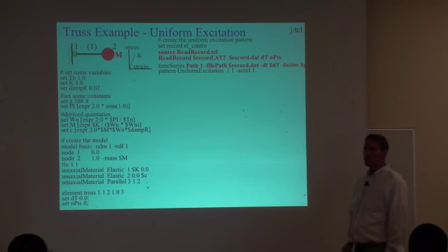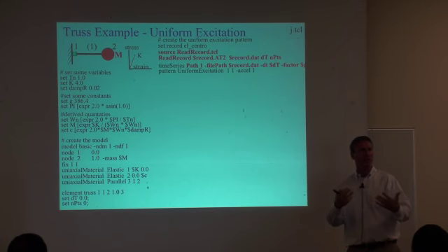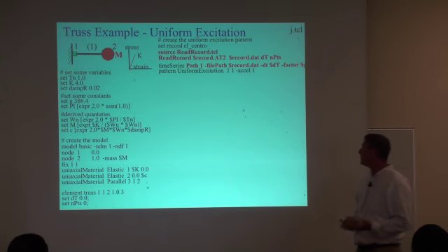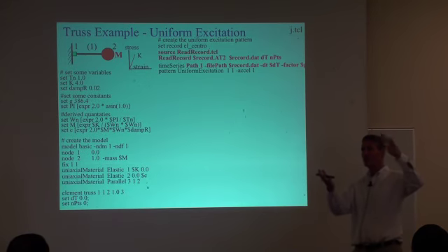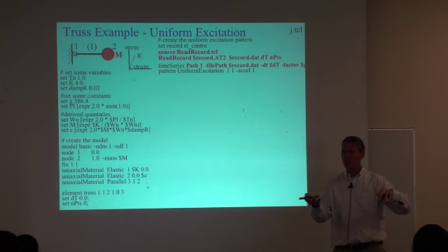Okay, now here's where I'm doing the uniform excitation. I've got three things going on here. We have a procedure, read record.pickle. That is just a procedure which will read a ground motion stored in the PEER format, which is .at2 format. It gives you information about where the record was located, the number of points in the file, and the delta T also in the file.